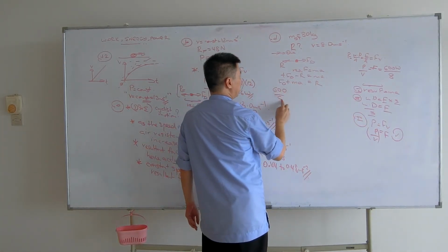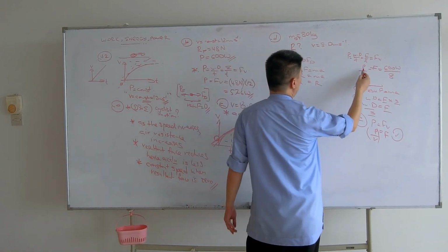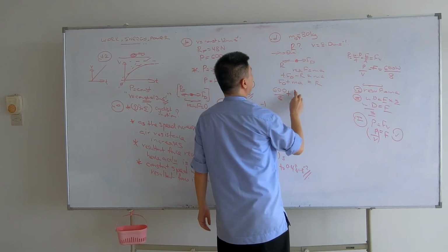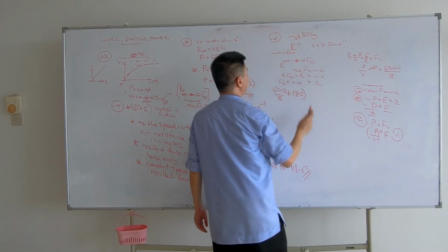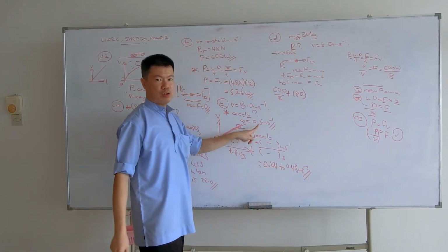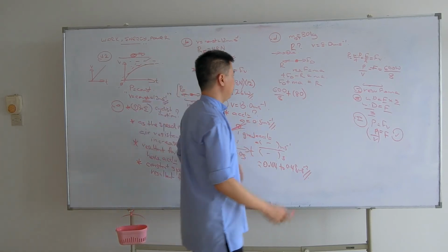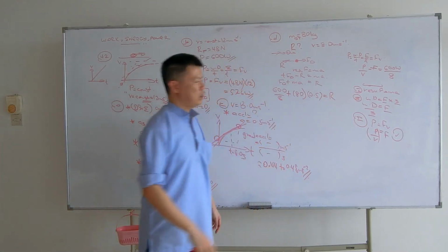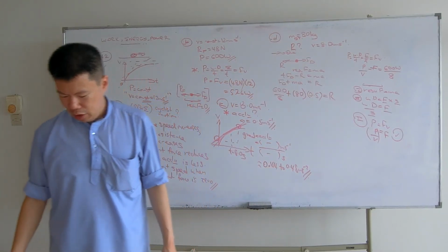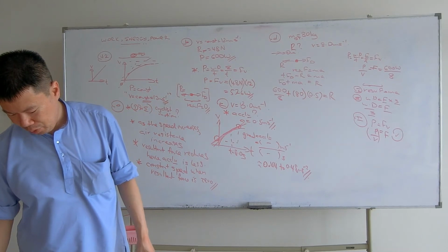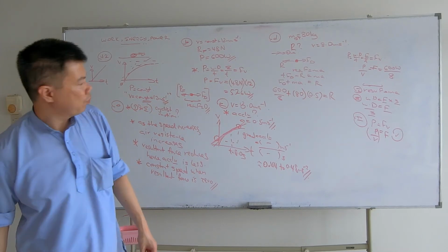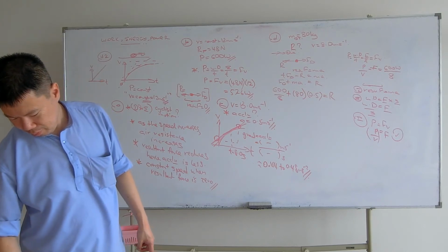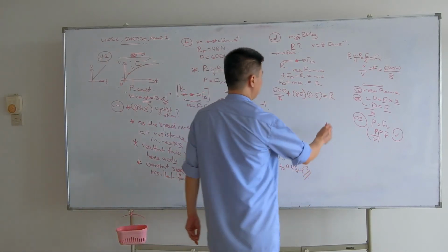600 over 8 for your driving force, because this is the power used to drive the cycle. Your M here is 80, and A is 0.5. It's a short question, so please use the exact value they want, which is 0.5. I don't have a calculator with me, so please calculate this. Once you finish calculating, you should have a value of around 32 newtons.